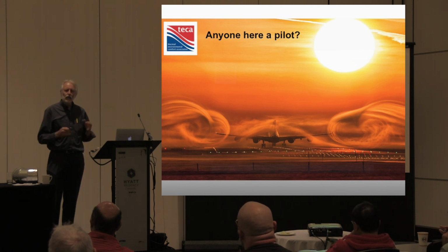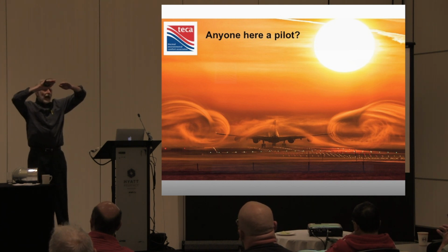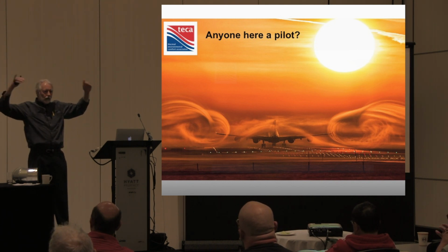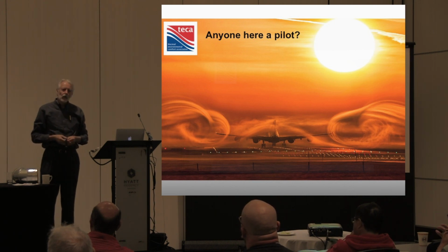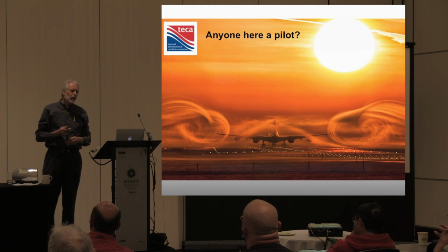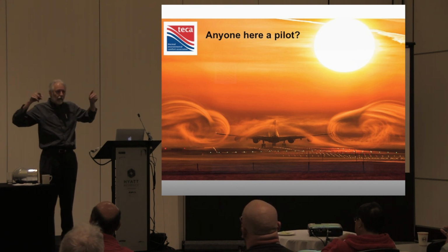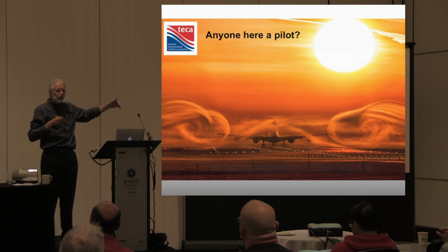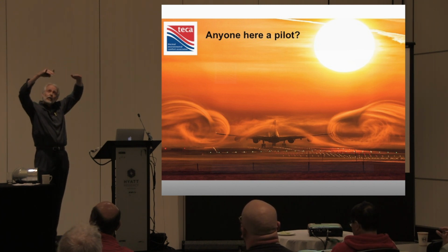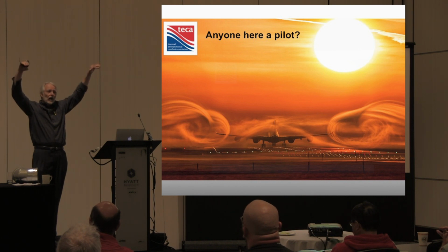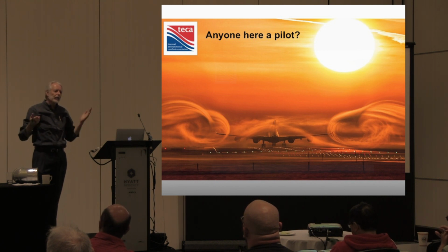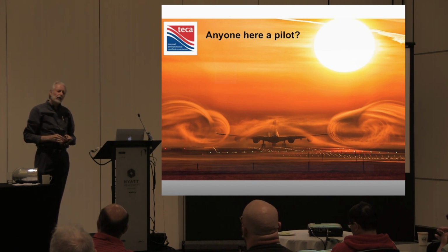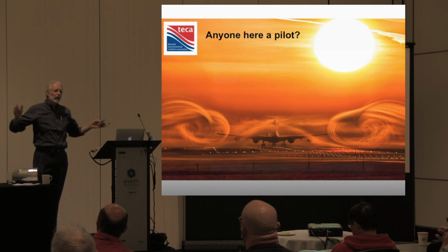But we ended up with, and we don't fully understand the physics, the carbon black that's in our city air charged going through the ducts and it's stained the ceiling all around the ventilation grills. I don't know the physics of it, but the particles of carbon black, which are very, very small respirable particles, got charged going through that duct. And when it came out of the ceiling supply grills, the Coanda effect made it stick to the ceiling, and the particles appeared to be far worse than it would have if it was a grounded sheet metal system. That's the only answer I can give you. The economics were not there, and the downside of the staining was the straw that broke the camel's back.